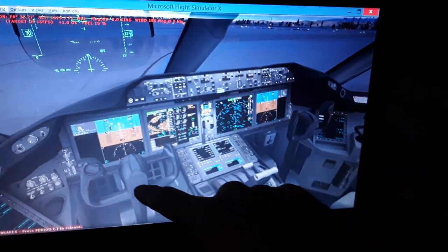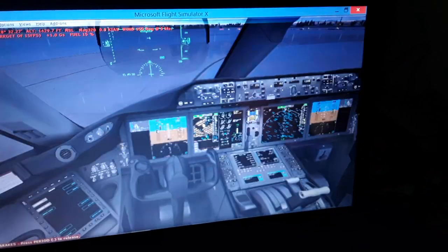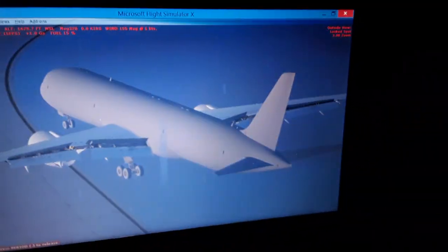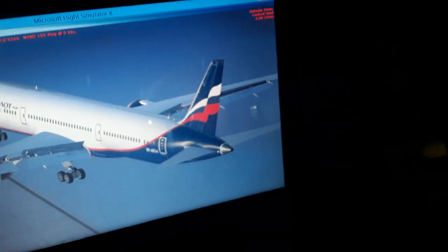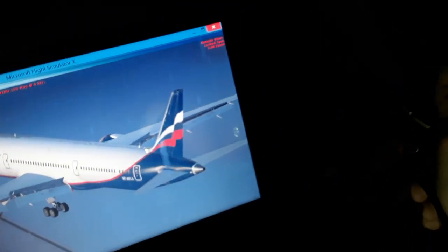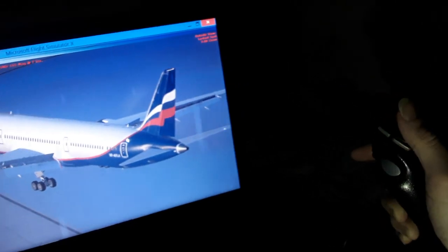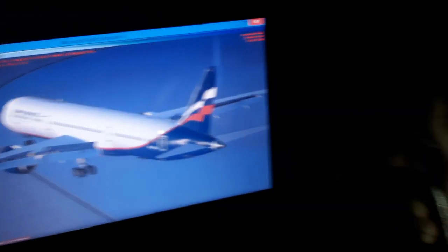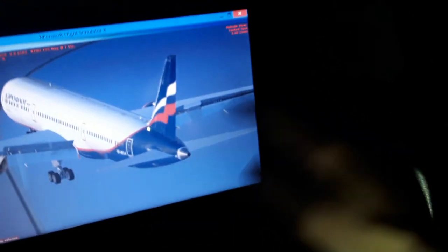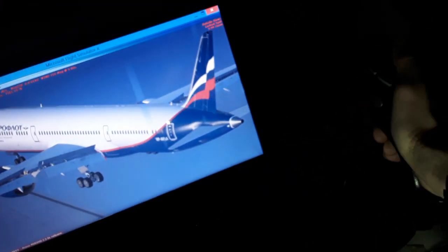We have the rudder aerodynamically effective from 45 knots over here. So you lose the forward nose wheel above 70 knots. You have only the rudder. The rudder is aerodynamically effective from 45 knots. So you use that for directional steering for yawing turns over here, as you can see. So this is the yaw,